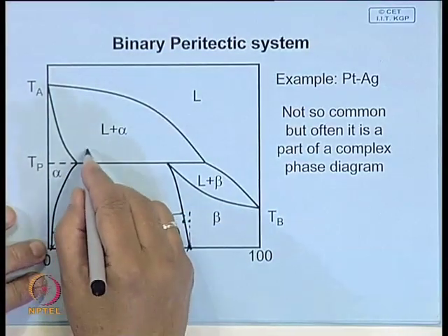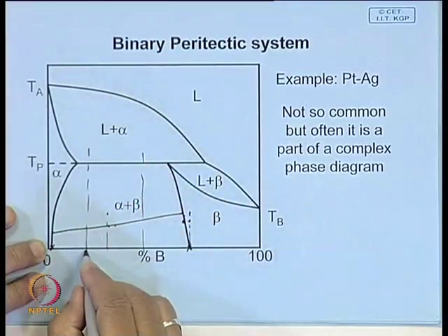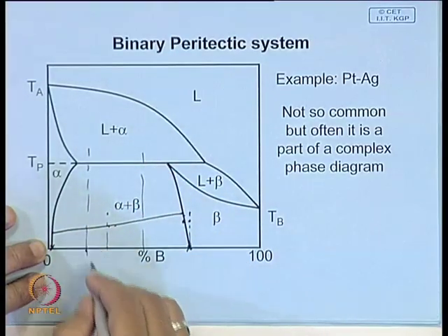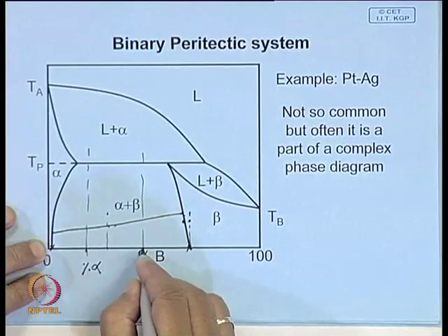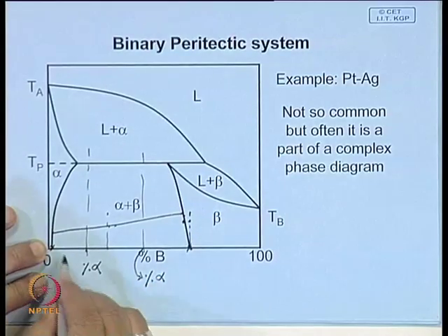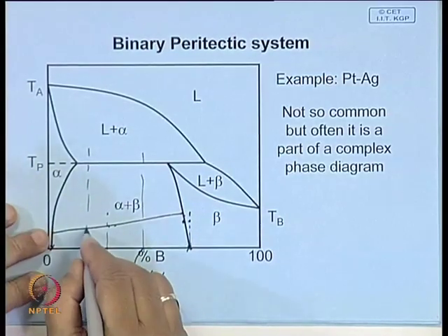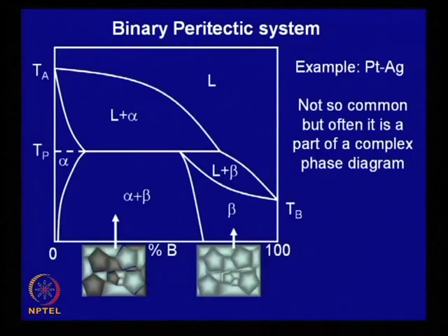So, what you have to do is look at two microstructures or two compositions, find out the percentage alpha here, find out the percentage alpha here, and in both cases, both phases alpha and beta will have a composition, alpha will have this composition, beta will have this composition.